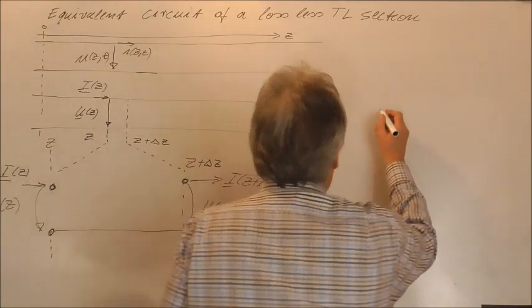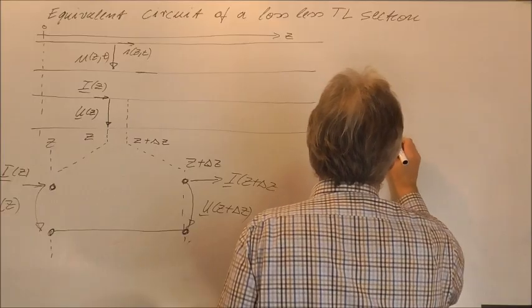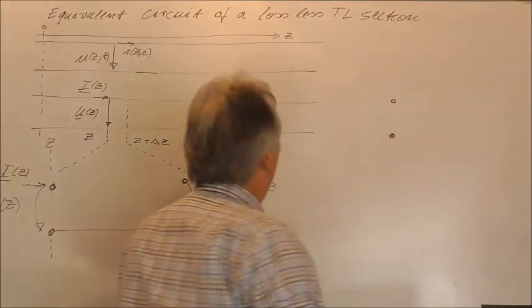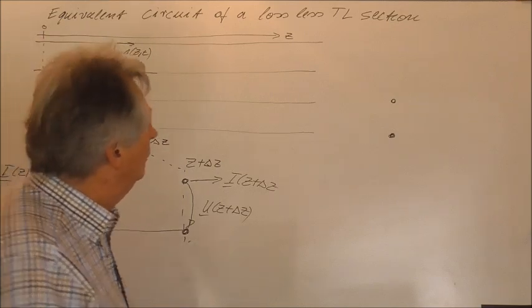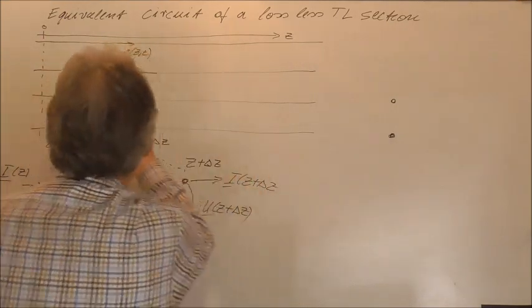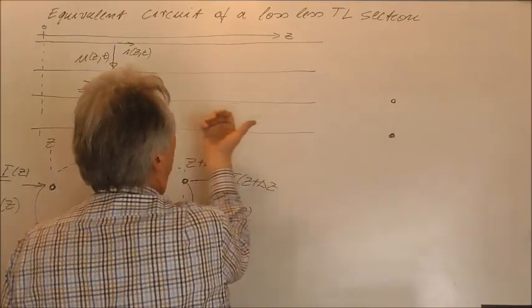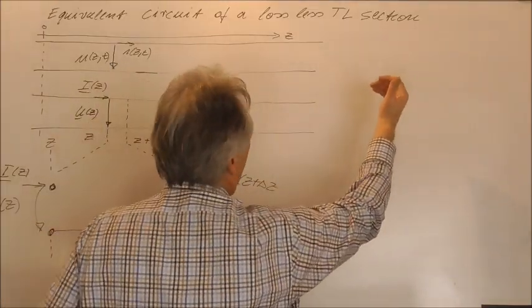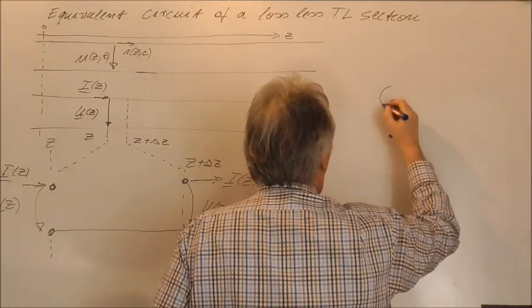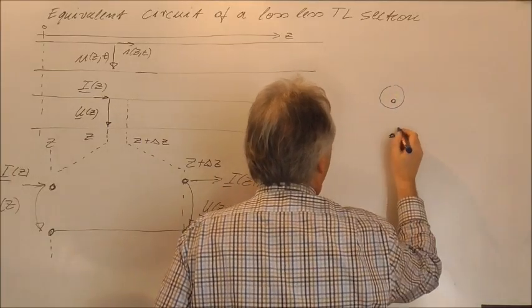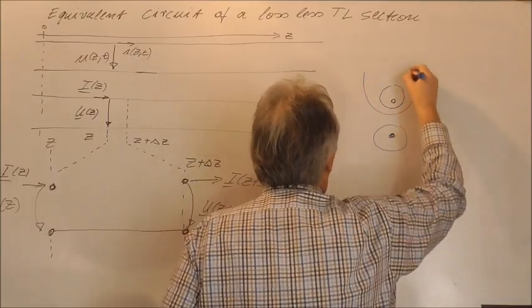Therefore, I want to sketch here again a two-wire line. We remember when we draw the two-wire line, of course, the current which we will have here is flowing in this direction. Here we have the z direction. This current will result in magnetic fields surrounding this line.